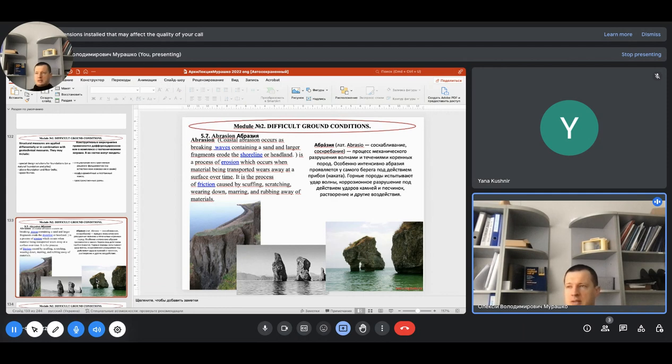And suffusion significantly differs from karst, because in suffusion we don't have chemistry, we have only a physical process of a water flow which replaces little particles of soil between the bigger particles of soils, and which can also lead to underground sinkholes of big diameters.